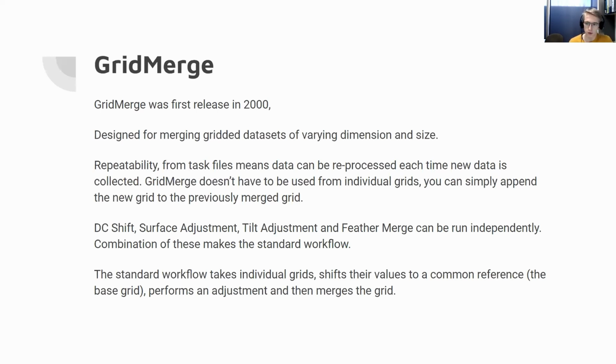So they're two strengths. The limitation of bringing a new grid into a pre-existing merged grid is that you should only do it a number of times. Each time you go over it, you're generating a least squares fit on top of a previous least squares fit. So we have a bit of a recursive generation of uncertainty. So it's recommended to not do that and to always start from the beginning or the earliest point possible.